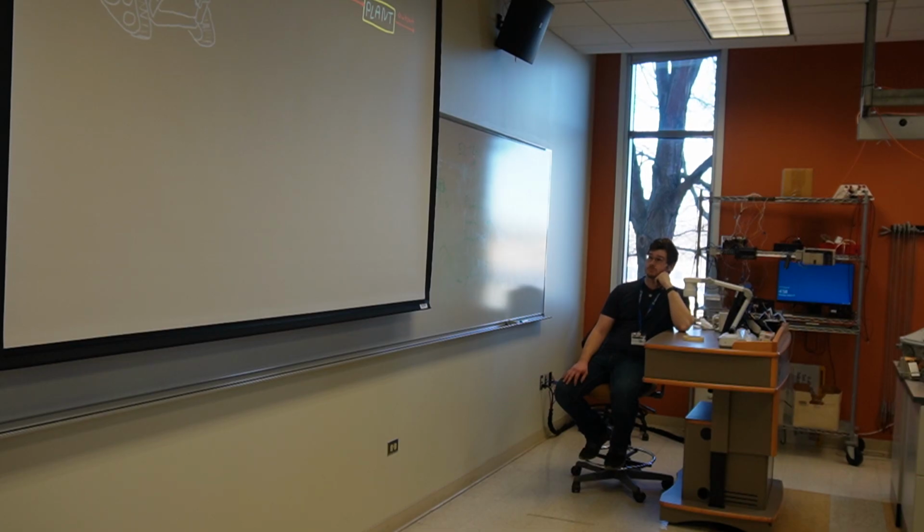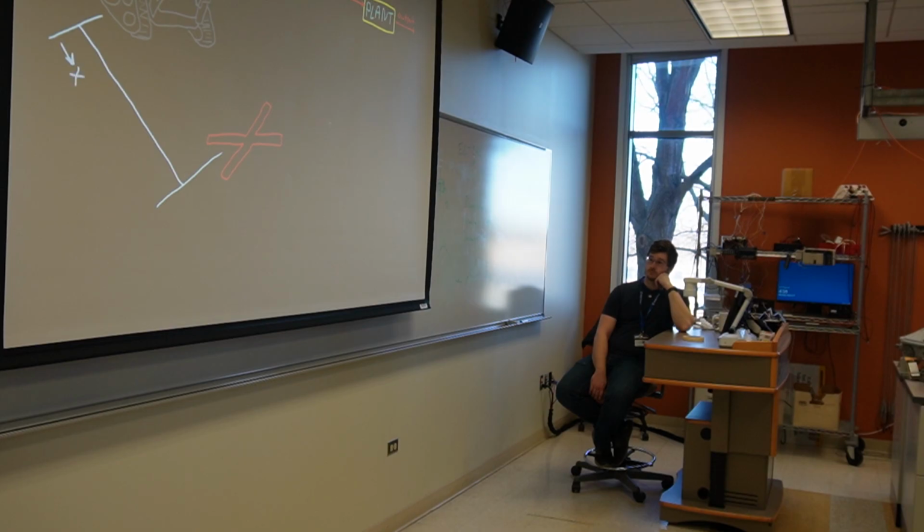You're tasked to build a robot that needs to move from this spot here over to this red X. You could figure out how fast the robot moves, and then from that determine how long the robot needs to drive for before it gets to the red X. This type of commanding is called open loop because the amount of time the robot drives is not adjusted based on the actual position of the robot. And open loop commanding is perfectly fine for systems that don't change much or where accuracy isn't as important.